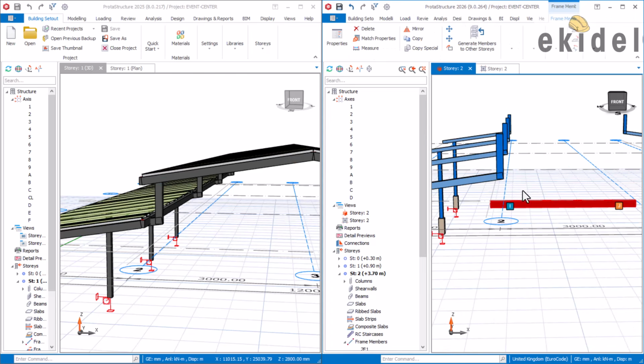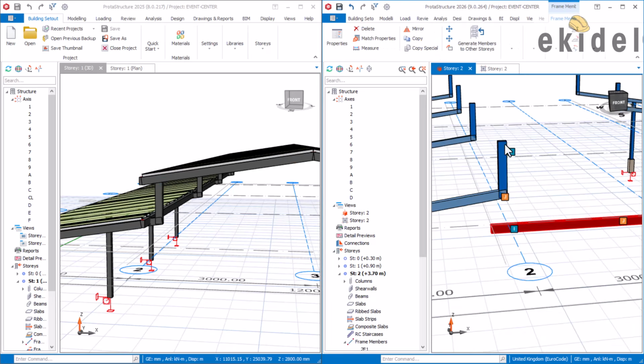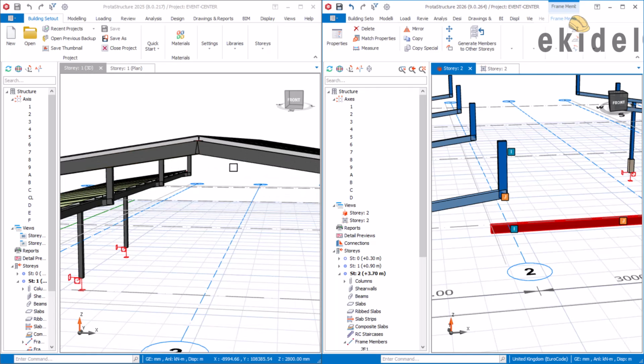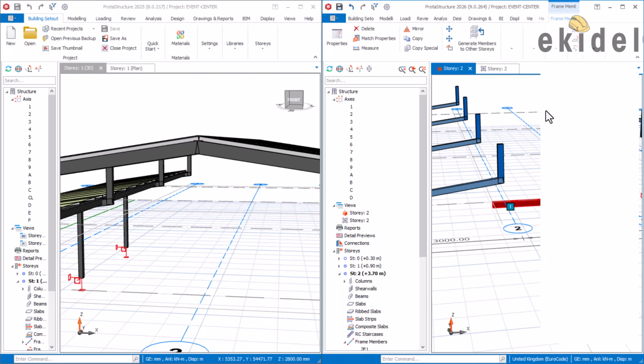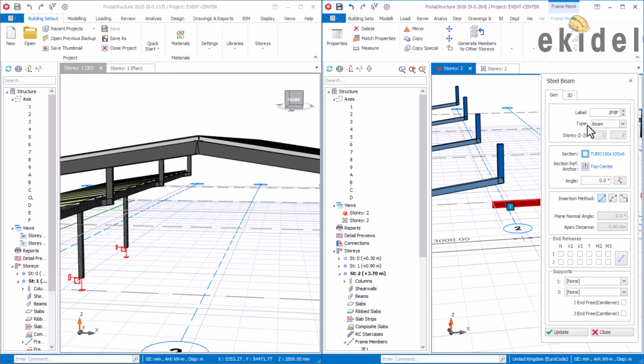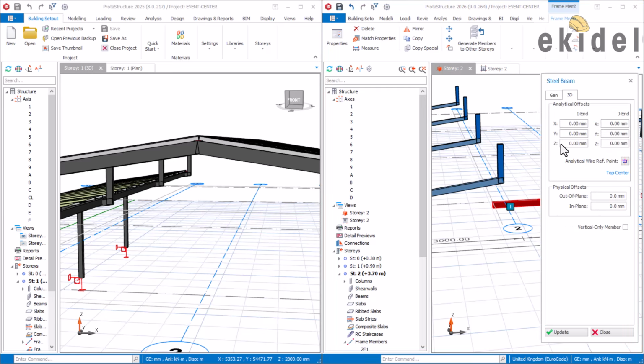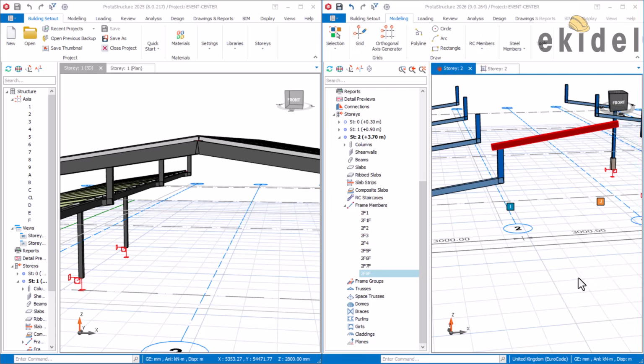To have this beam at the top here and also inclined as this is inclined here, I'll click on this beam, right click and say property of the beam, and then click here and type in the value 15, that's the value, and then here 2000, that's the value, and I'll click on this. Okay, that is fine. So you can see that right now.